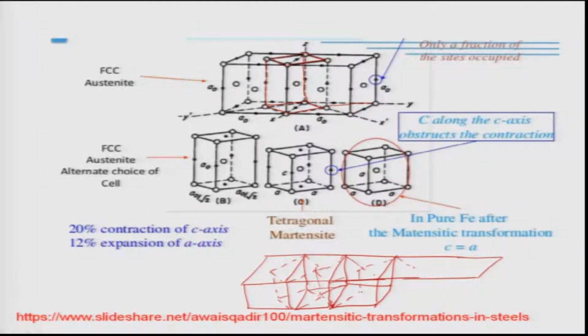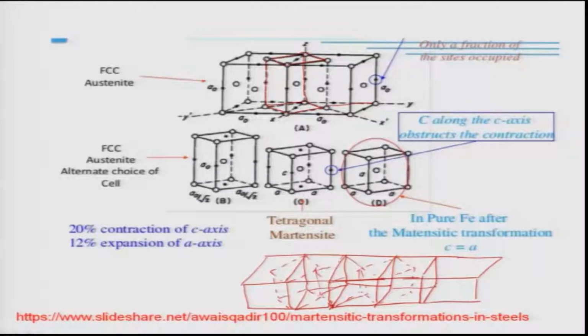So what is the moral of the story? The moral of the story is very simple: if I want to transform austenite to martensite, I need to simply connect these unit cells and move a little bit. So it's just like a chain reaction. The originally aligned FCC unit cells simply get shuffled up because of these situations. They are like a pack of cards. You are rotating them to the directions to make this BCT unit cell possible.